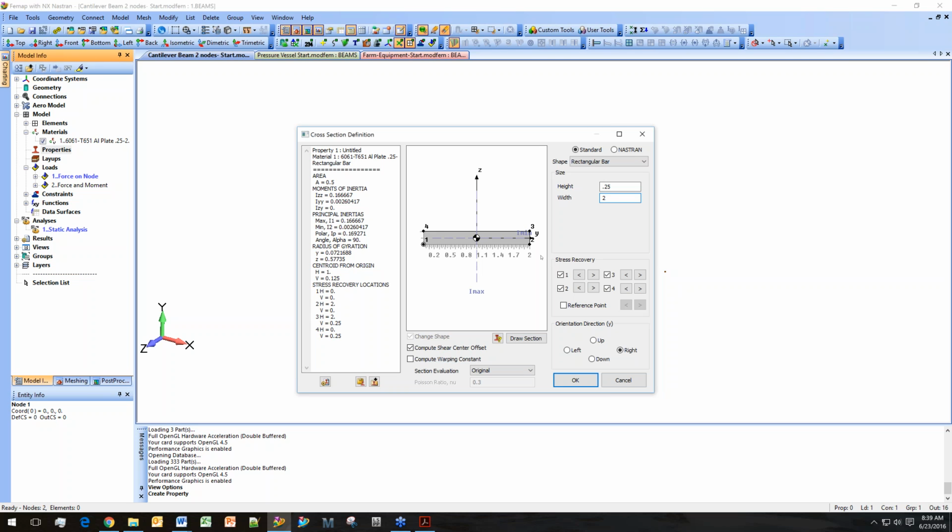You're getting stresses calculated at each of these points, and that's why we'll look at the result set later on, and you'll see there's end A and end B points 1 through 4 stresses. If you want to move these around, there is the option to. You've got these buttons down here. You can shift them if for some reason you're really interested in the stresses along the center line at the bottom. But most of the time, we just leave them at the default orientation.